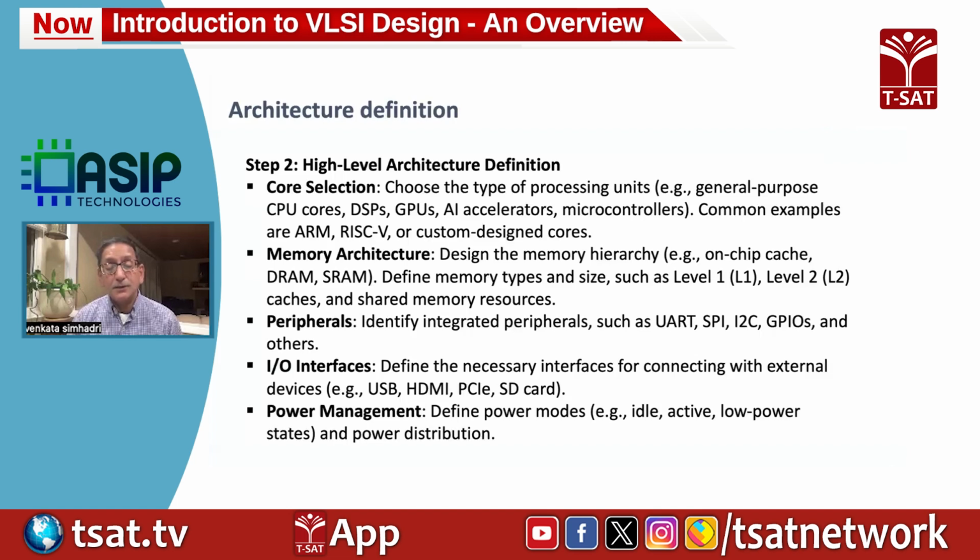Then we have talked about power management, whether the SoC gets into an idle mode or a low power mode when it's not processing, or whether there are any modules in the SoC that you want to put in a sleep mode or shutdown mode to optimize the power. So those decisions you have to make at the architecture definition level.